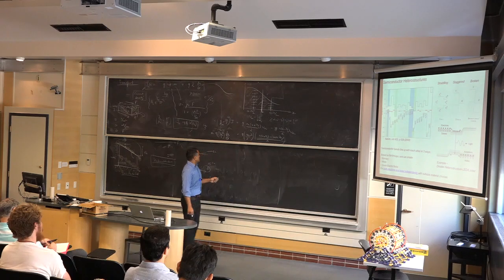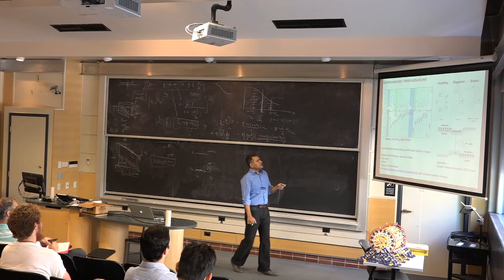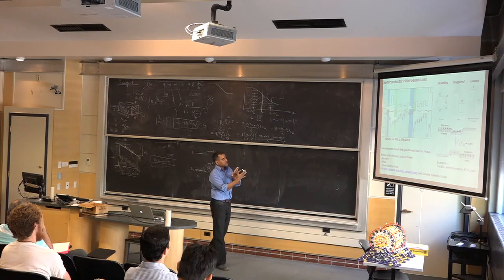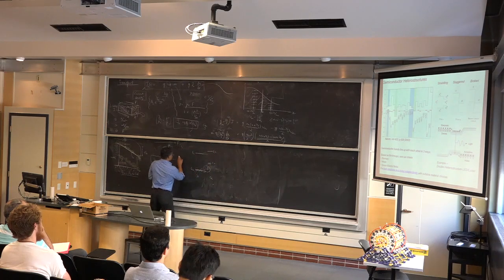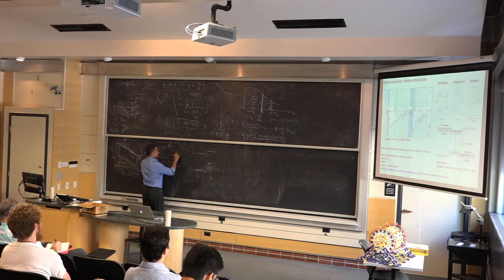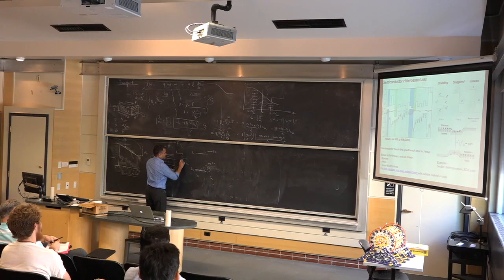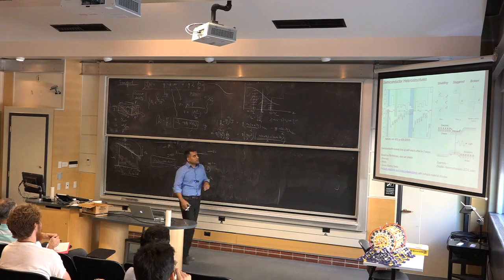And so this sort of alignment we just saw, where the conduction band is lined that way, valence bands are lined that way, is called a type 2, sort of called a staggered heterojunction. This is a heterojunction between two materials. It's called type 2, where you can see it's a staggered thing. You can have a situation where the narrow band gap material is completely contained within the wider band gap material. You can have alignment that looks like that between two materials, and that would be a type 1 or a straddling.